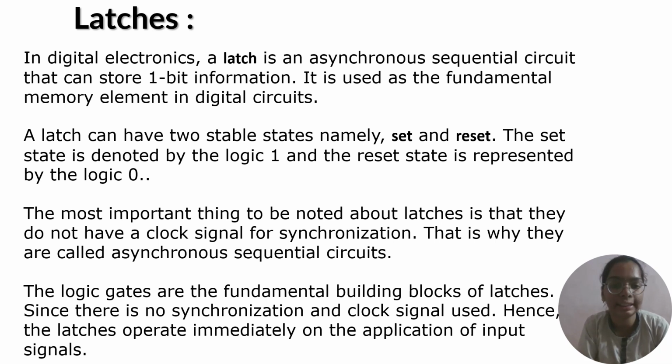What is a latch? In digital electronics, a latch is an asynchronous sequential circuit that can store one bit of information. It is used as a fundamental memory element in digital circuits. A latch can have two stable states, namely set and reset. The set state is denoted by logic 1 and the reset state is represented by logic 0.